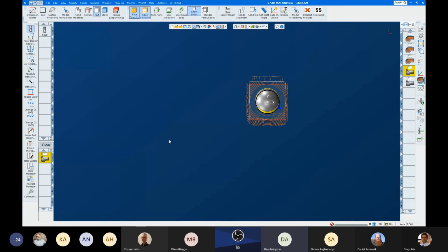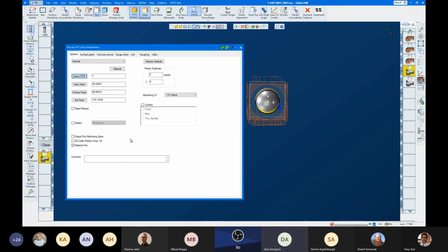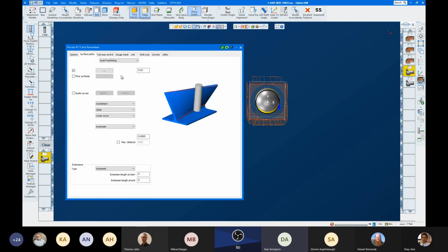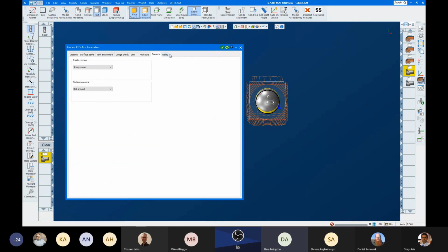And if it's a roughing toolpath, the toolpath will be trimmed to the material. Just a few notes or cautions here. This is our page in ModuleWorks, a page that we create, and that's where the material only checkbox is. However, there are options such as swarf machining, where you don't define stock.